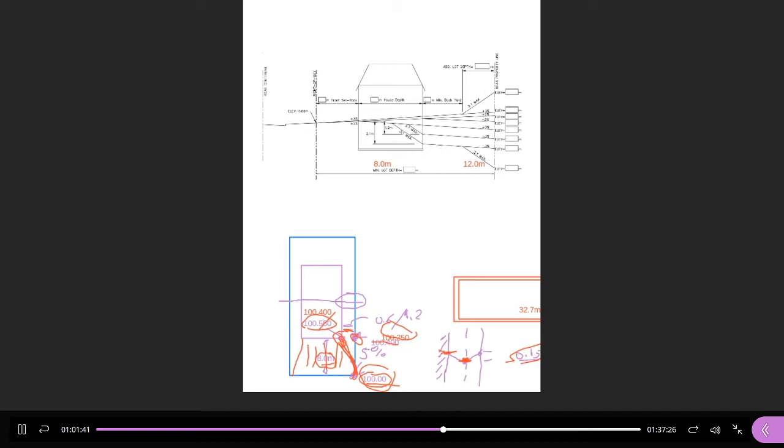So what would it be? I'm going to put it on the drawings in a second. I'm going to put it here. It would be positive 0.98 meters. Okay. So if the backyard was about a meter higher than the front, you'd have a front draining lot where the entire backyard is usable. It's 3%, maximum 5% internally. And that's great. That'd be good if I could use the entire backyard.